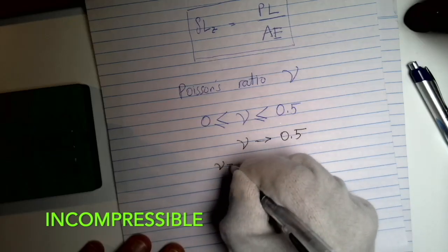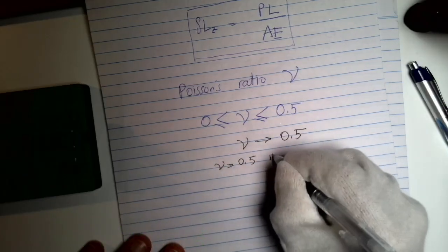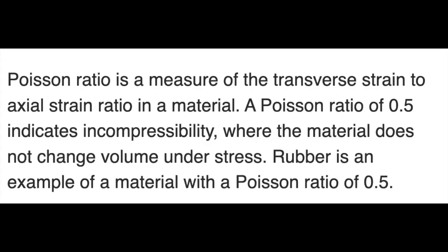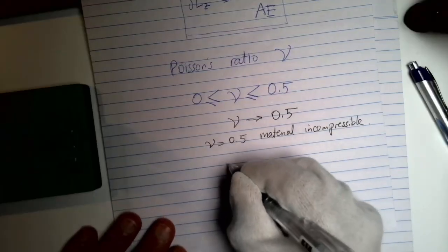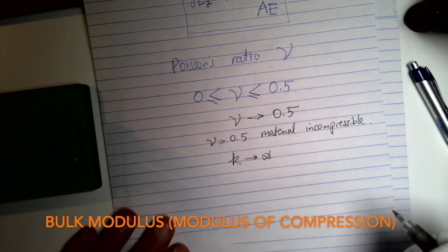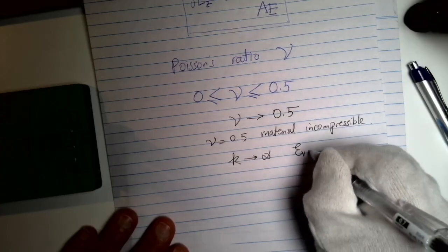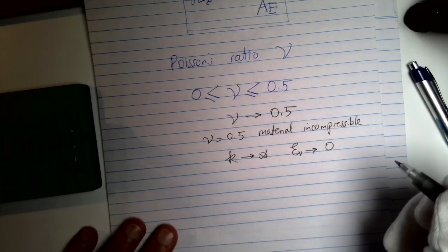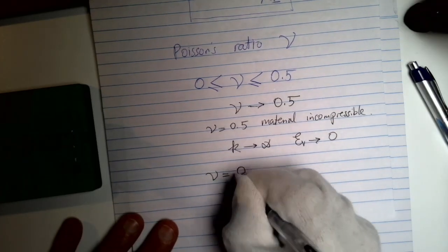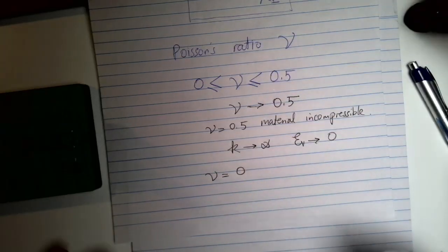For Poisson ratio 0.5, the modulus of compression becomes infinity, or volumetric strain goes to 0. There's no volume change. It's incompressible. As Poisson ratio approaches 0, the material is very compressible. The volume changes when you apply the stress.